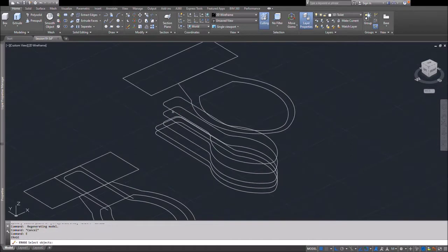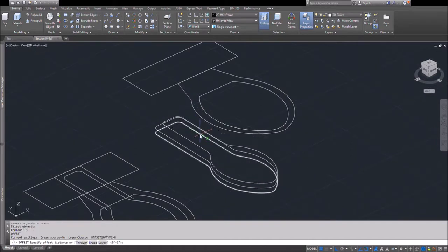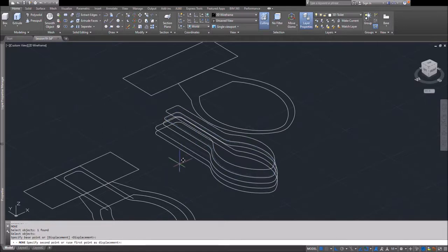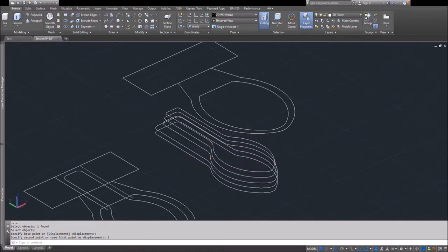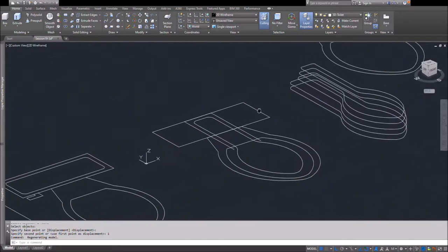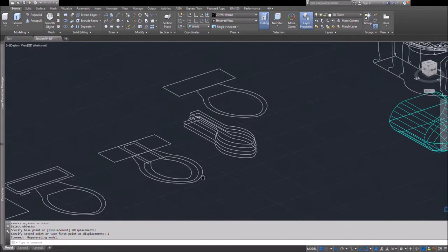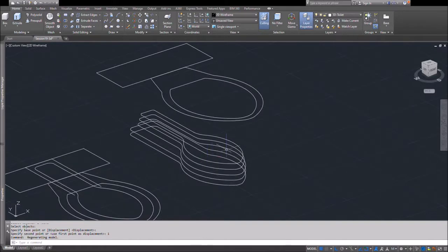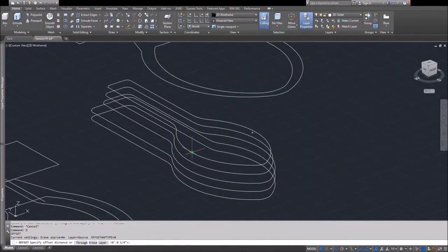And some of the profiles are actually the same profiles, right? If the part that I'm drawing is basically an extrusion, and if I'm cutting it a couple of times and it's really the same profile, I could just copy them twice or three times, so that I have an area where that extrusion will match those profiles, right? So as I do that, I'm also panning and orbiting around the model to see if the profile is really looking like what it's supposed to. And as I need to make edits to it, I'll continue to edit those contours of those profiles, right?